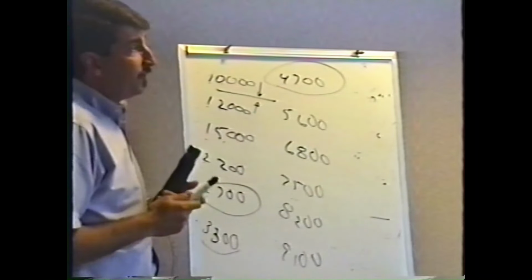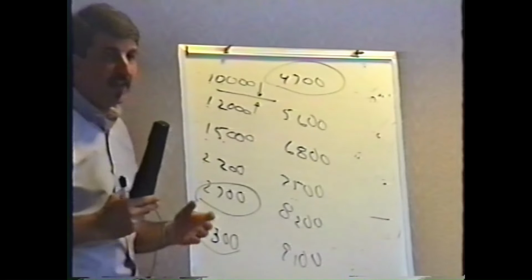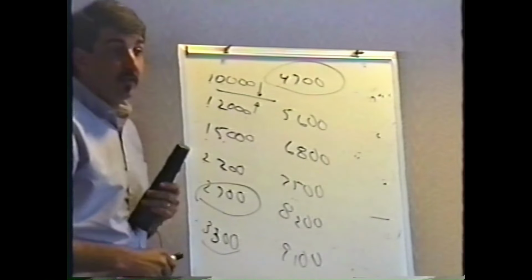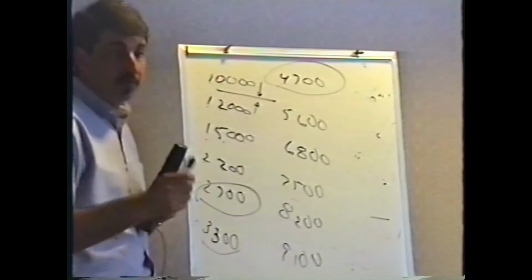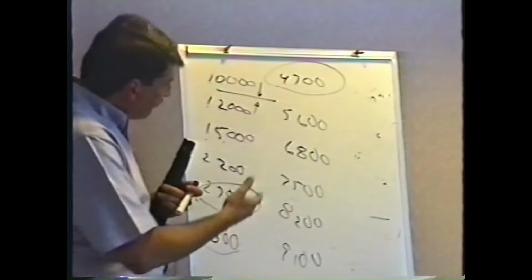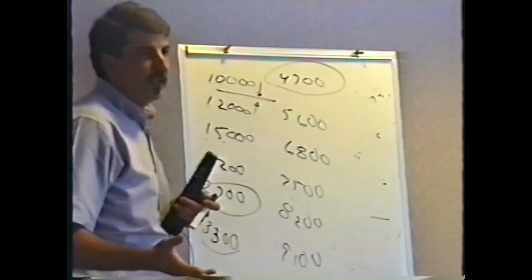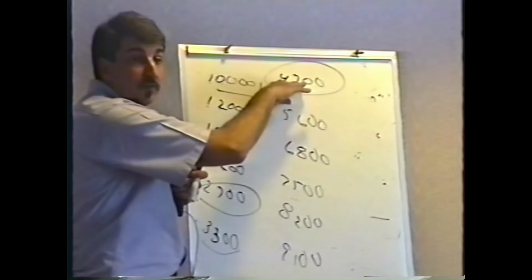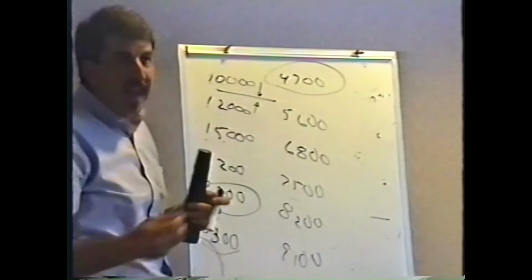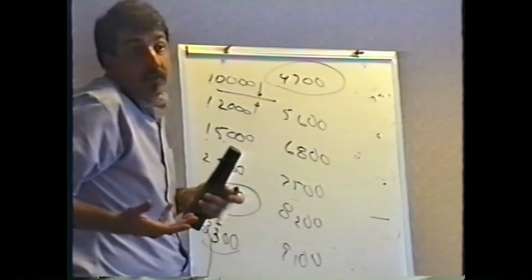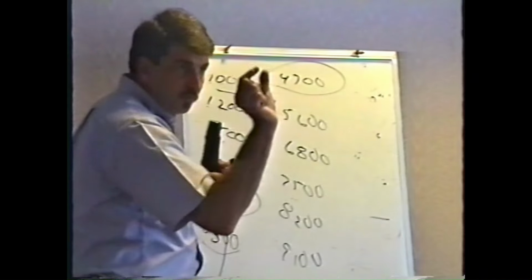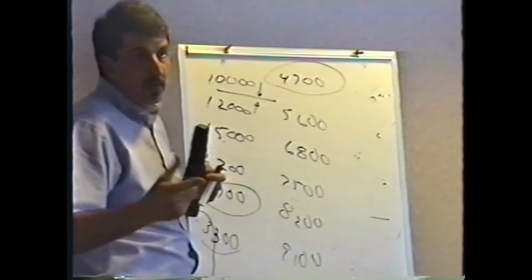You look at a resistor. For instance, if somebody tells me that they've got a resistor that's 73 ohms or 730 ohms, I can say almost without a doubt, bullshit. You don't have that resistor because they don't make that resistor. How could you possibly have it? If somebody says, I've got a resistor that's 5,000 ohms, bullshit. You might have a 4,700 ohm resistor, or 5,600, but you probably don't have a 5,000. They make them, but they'd be like precision resistors that we just wouldn't use. So you see the same maybe dozen first 2 color combinations over and over and over again, and the only thing that changes is the multiplier.